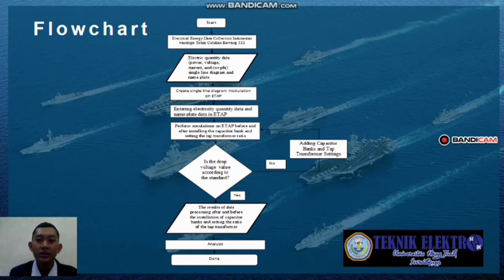This is the flowchart of my research. I start from start, then electrical energy data collection of the Indonesian warship Teluk Celukan Bawang 532, then electrical quantity data like power, voltage, current, and cos phi, single line diagram, and nameplate. Then I create the single line diagram modeling in ETAP. Then I perform simulation in ETAP before and after installing the capacitor bank and setting the tap transformer ratio. Then see the result whether the value of the drop voltage is according to the standard. If not according to the standard, a capacitor bank and tap transformer setting will be added.